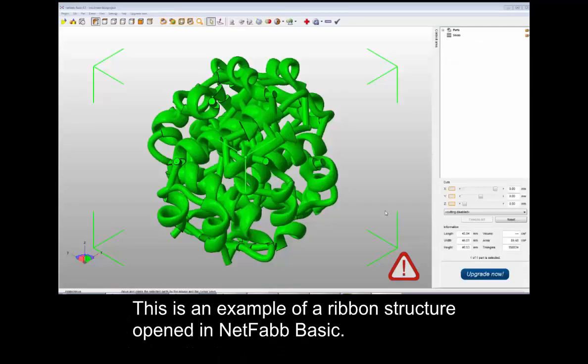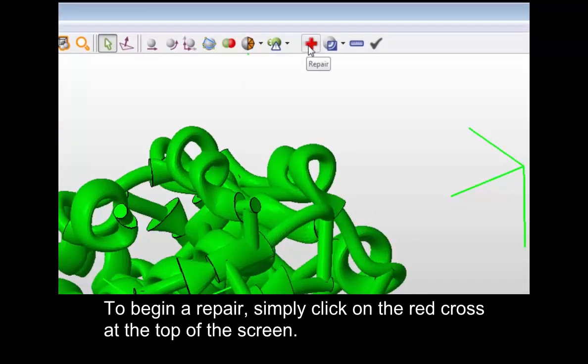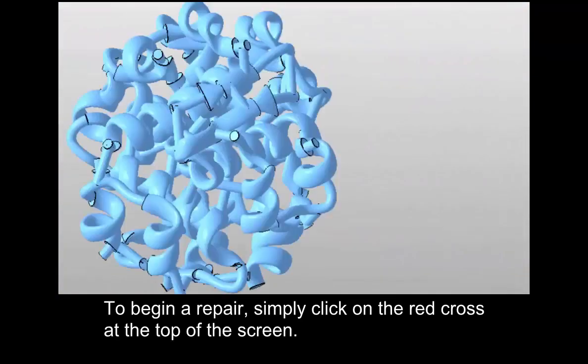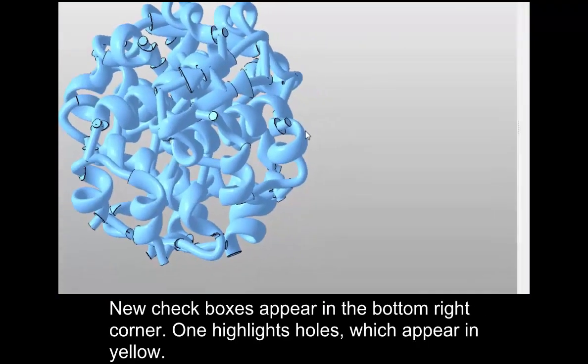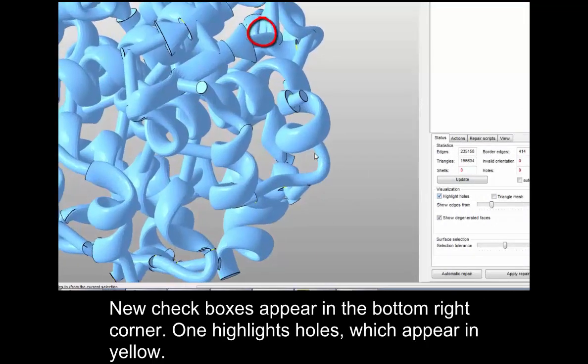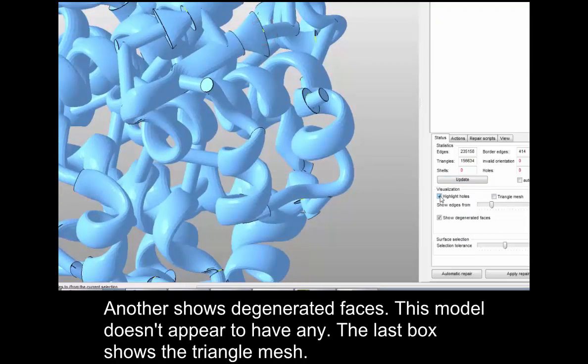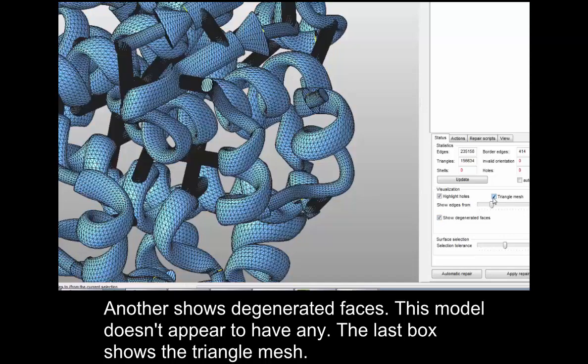This is an example of a ribbon structure opened in Netfabb Basic. To begin a repair, simply click on the red cross at the top of the screen. New checkboxes appear in the bottom right corner. One highlights holes, which appear in yellow. Another shows degenerated faces. This model doesn't appear to have any. The last box shows the triangle mesh.